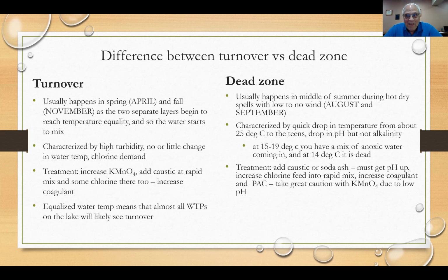If you keep that pH too low, which often happens to operators, you're going to get manganese in the system. And days later, you're going to get yellow water complaints. If you're going to use the permanganate, that's fine, but you better be on your toes because it will get past you in a heartbeat. So think about it.